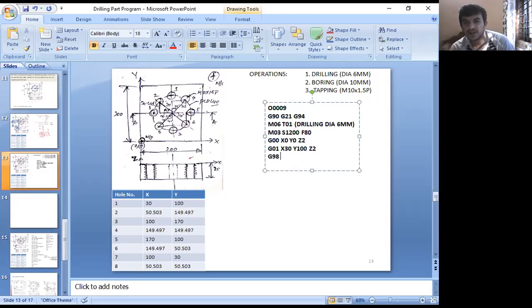Whether I go for a drilling cycle or a peck drilling cycle? Give me the answer. Do I want to produce a deep hole, where the depth of the hole is greater than the diameter, or only a shallow one?